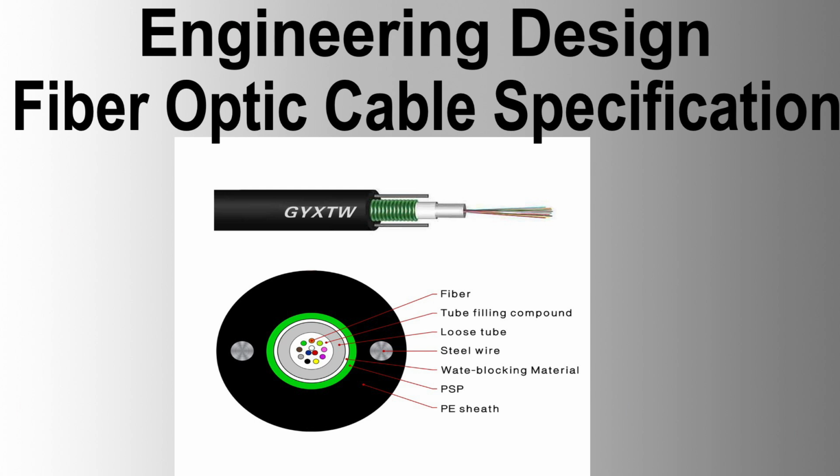OTDR typical requirements. A recording optical time domain reflectometer, OTDR, will be utilized to test for end-to-end continuity and attenuation of each optical fiber. The OTDR must be equipped with data storage, printer, help feature, compare trace features, and OTDR software. Data trace labels: fiber identification, ID, with a minimum of 10 characters. Cable ID with a minimum of 10 characters. OTDR location with a minimum of 20 characters. Far end location with a minimum of 20 characters. Test operator initials with a minimum of 3 characters.